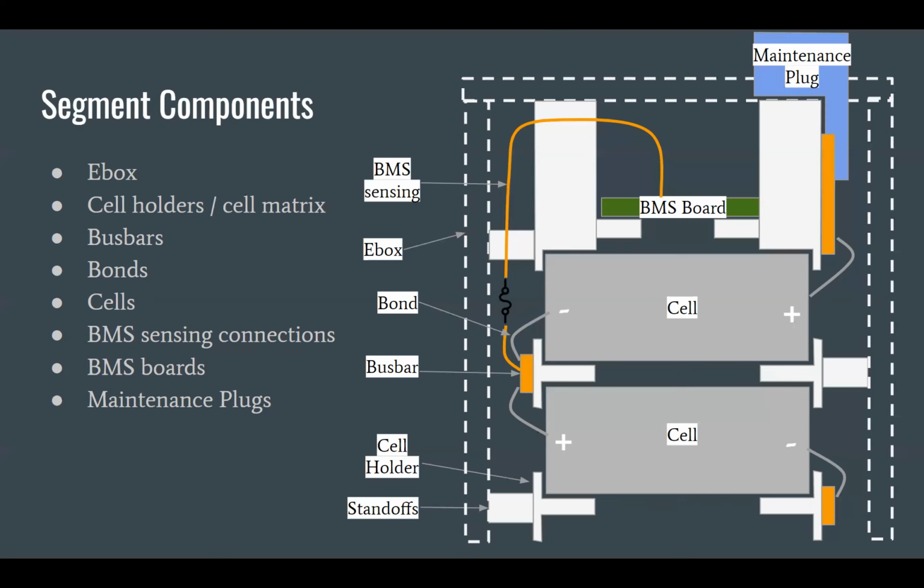So obviously I'm not going to pop this one out. Number one, because if we take them out, we have to wear gloves, because once you go above 60 volts, you're at risk of electrical shock or damage to yourself. And this battery pack goes up to 84 volts. So for safety reasons, we're not supposed to do that.